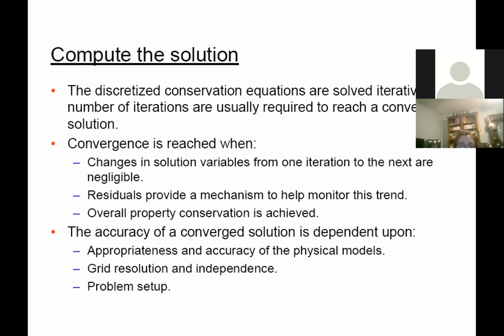Oh, you know what relative error is, right? The current value minus the previous value divided by the previous value, that will be a relative error. Relative difference, okay? If the entire domain, every point, the relative error compared to the previous time at every point, you have maybe thousands of points in your space. Then check every point. If all of the points have a relative error smaller than the criteria you specify, then Fluent will stop the iteration. So that's something you need to specify. It's a convergence criteria.